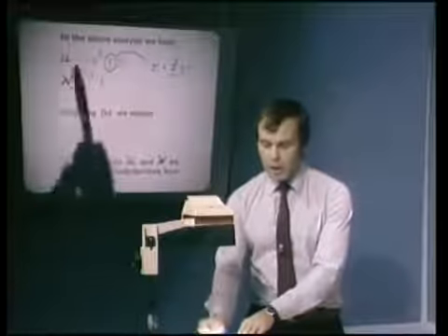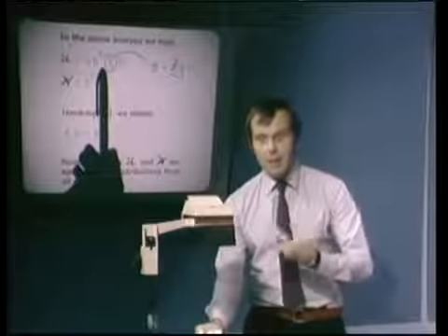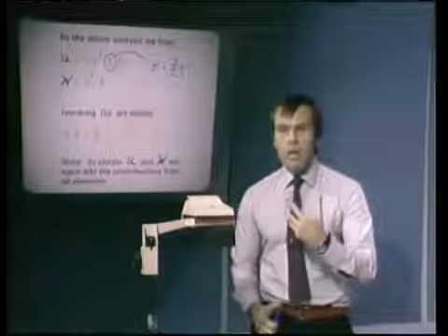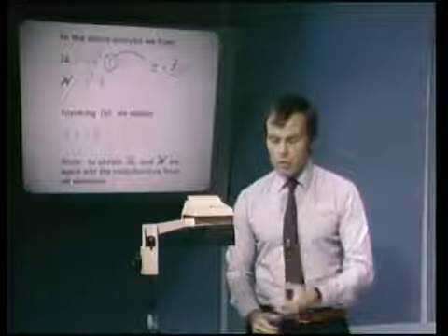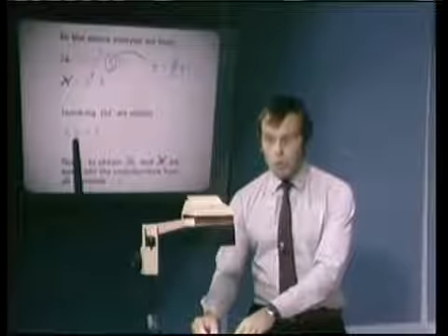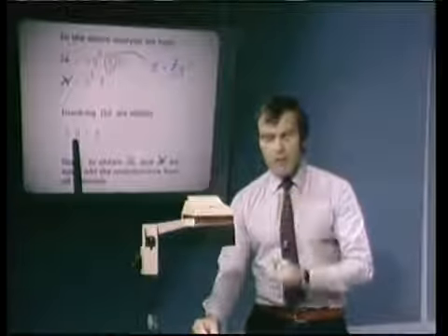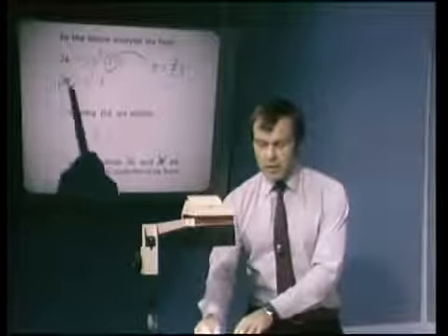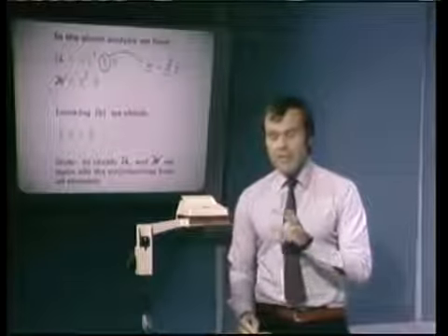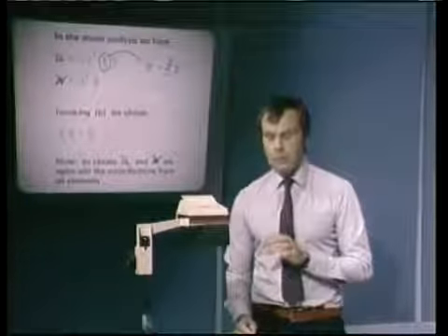It might be of interest to us to calculate this in order to find out how much strain energy is put into individual elements in finite element analysis. But this is only done if you want to evaluate error norms on the finite element solution and so on. If we only want to calculate Ku equals R and obtain the U's, in other words, to be able to predict the displacements and the stresses in the elements, then we would not calculate these two quantities. Now, this then were the essence of the analysis of a steady state problem for discrete systems.